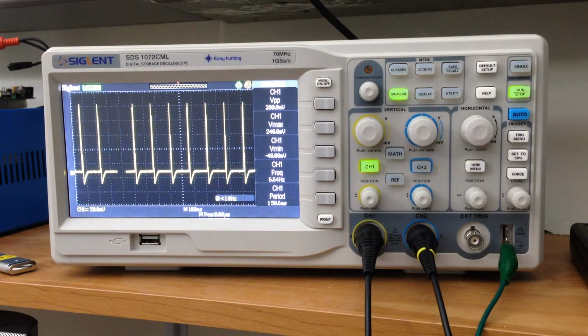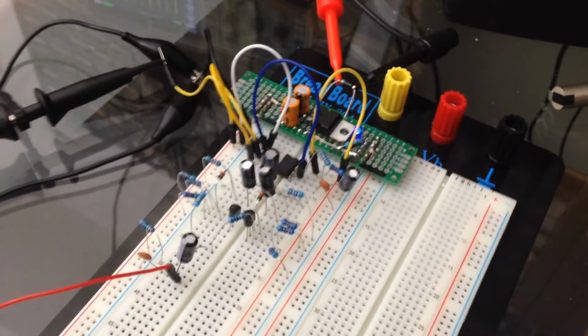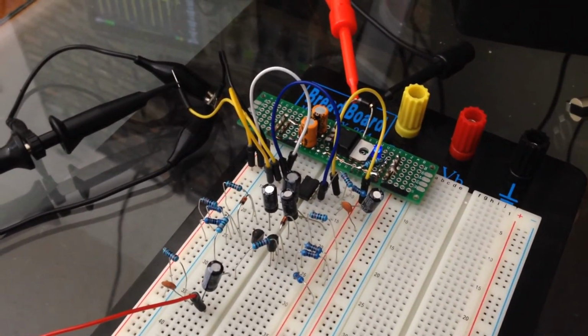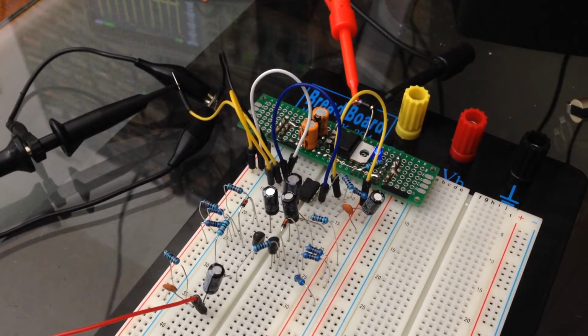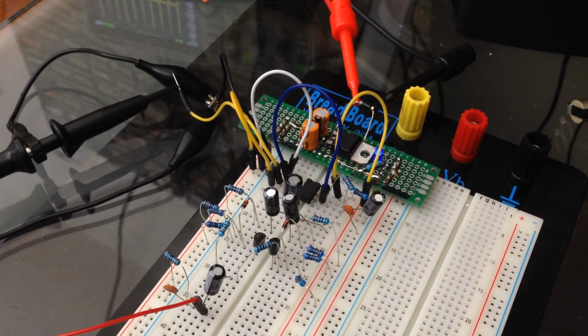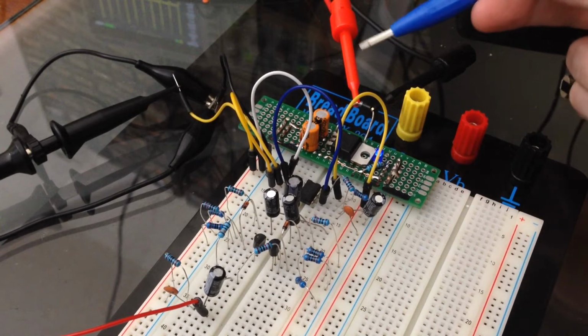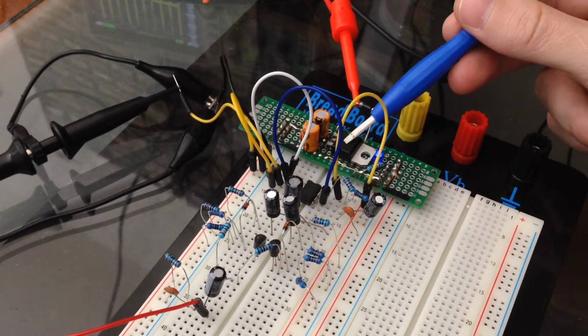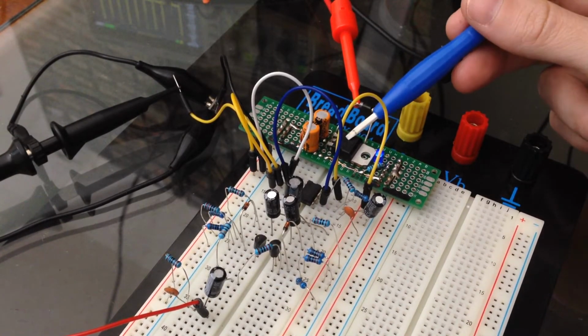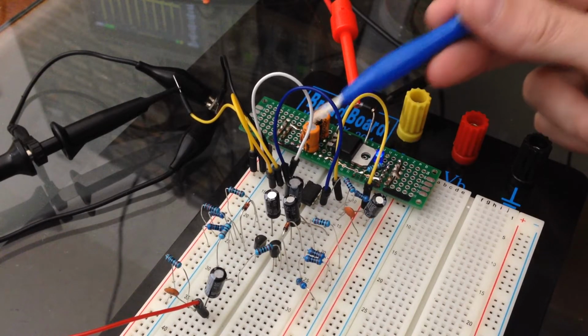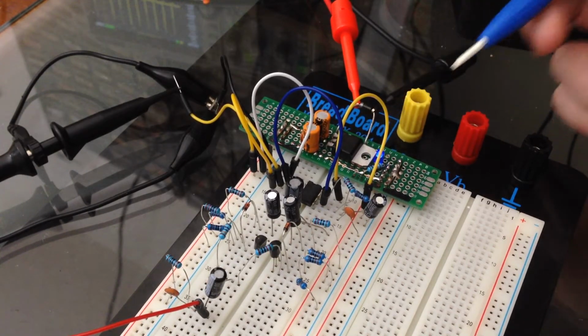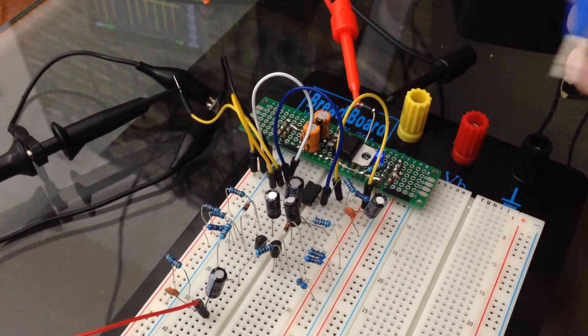And the cool thing is that this circuit is realized using entirely analog circuitry. So this is the circuit that I made, and I'll walk through it in a minute. But first, let's summarize how this works. Up top, I have 12 volts coming in, and I have an LM7805 linear voltage regulator with some capacitors here to smooth out the output. But this circuit is entirely powered by 5 volts.